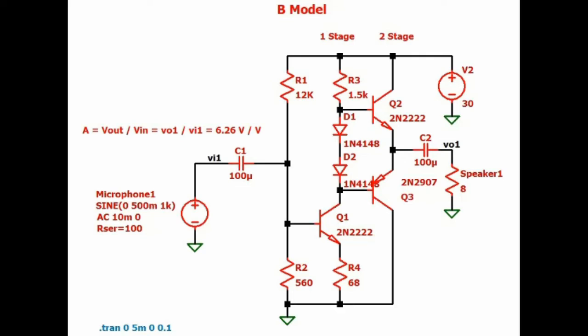In the second activity, in general, what we do is a two-stage circuit which allows us to amplify with a common speaker the signal that comes from a common microphone. For this, we decided to use the amplifier circuit model B, seen in class, for the good amplification that this produces in relation to the other models. The values taken into account for the speaker and the microphone were such that the condition of amplifying the signal so that it was heard up to at least 5 meters was theoretically fulfilled.